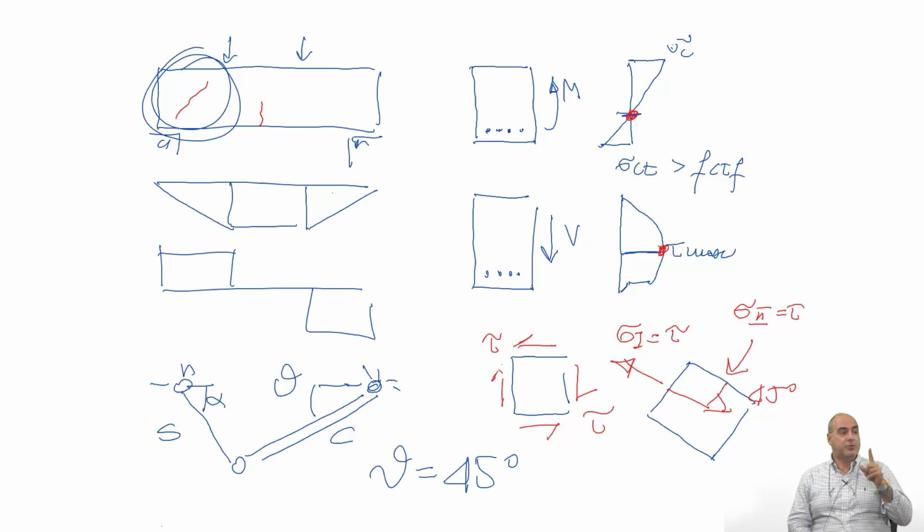So it's true that the steel is the ductile part of the couple. But it's also true that if you put too much reinforcement, your failure mechanism risks going into the over reinforcement. So you do no longer exploit the ductility and you have a brittle failure and the steel is still elastic. The other reason is, as always, money, because putting steel costs.